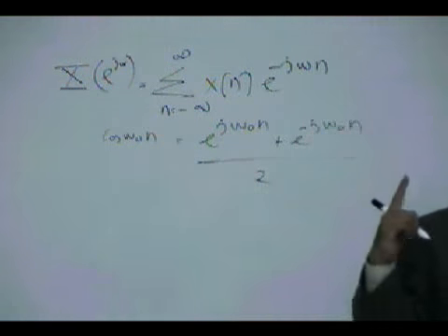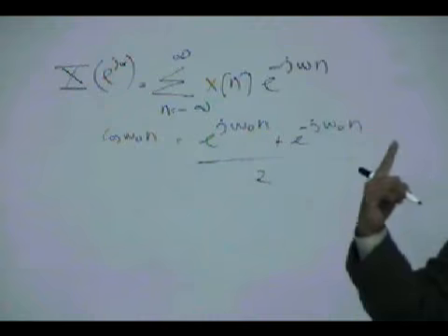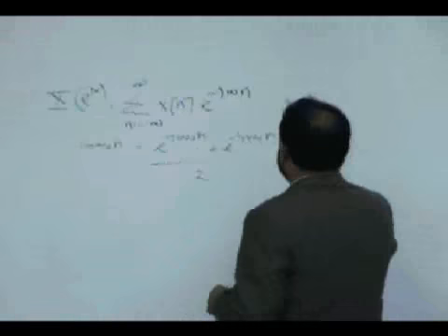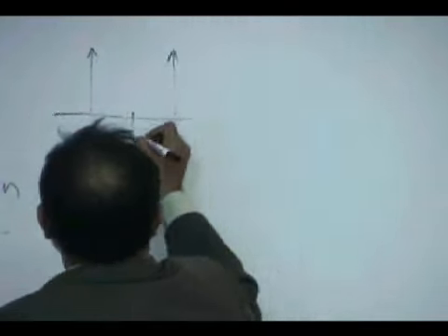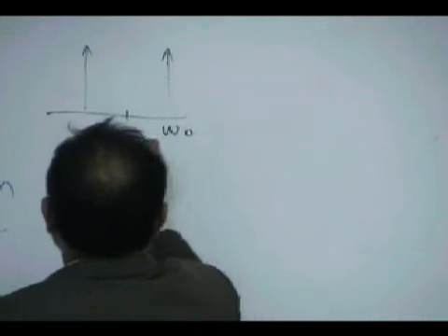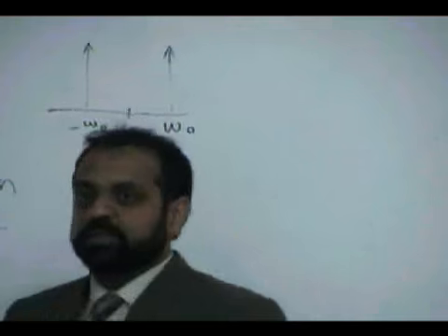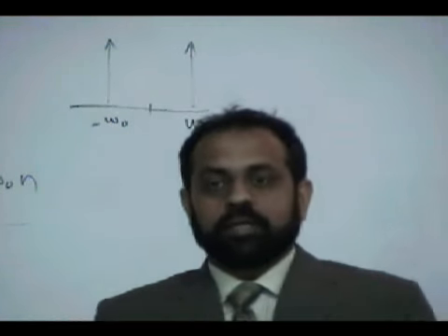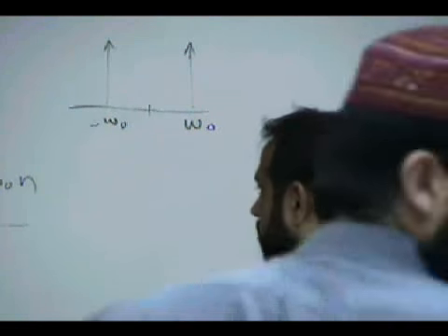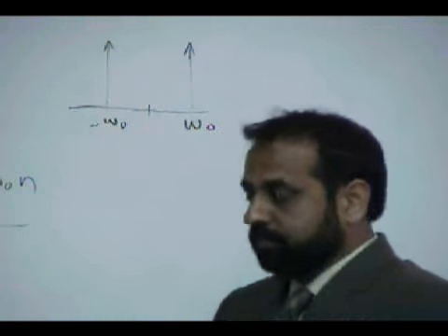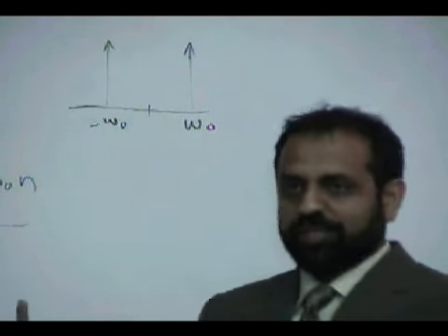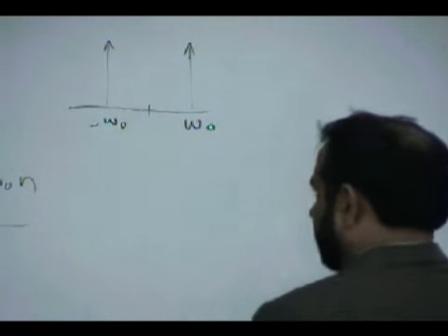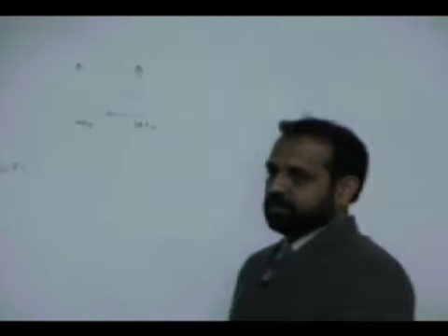So at these locations I'll get two impulses. So this tells me that there are two complex exponentials at omega naught and minus omega naught. So one frequency, but because the discrete time Fourier transform is about the exponentials, that's why in a cosine you see two of these. Okay, one on the right hand side, the other one on the left hand side.